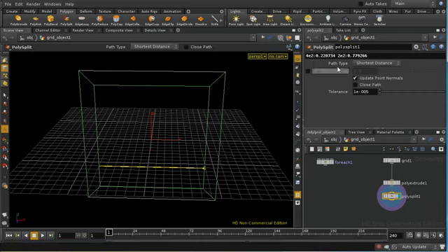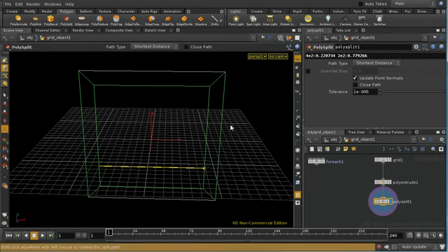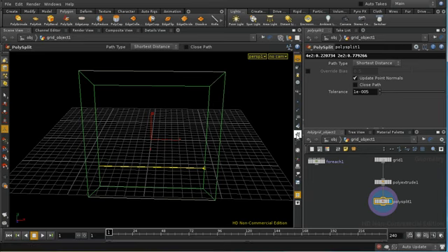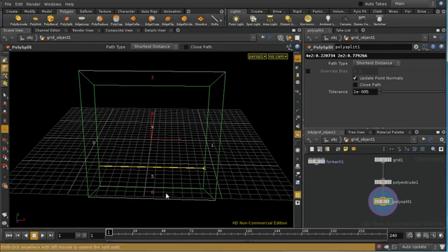Now the poly split tool in fact works relative to the length of the edges anyway, so we don't need to make that relative to the bounding box. Now, one thing that we can be confident of is that Houdini will approach this process in an identical way each time it applies these nodes. So providing we start off with a single primitive, the primitive numbers will remain consistent through each loop of the ForEach SOP. So every time I do this, primitive number 5 will be the bottom part of this split polygon in the middle.